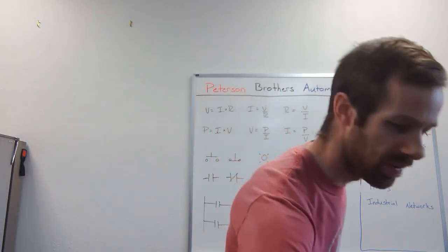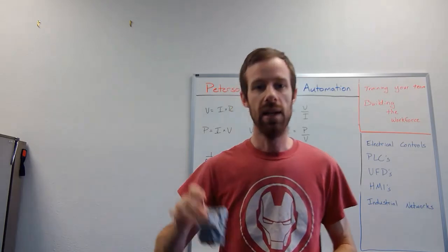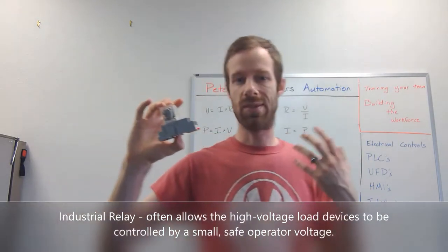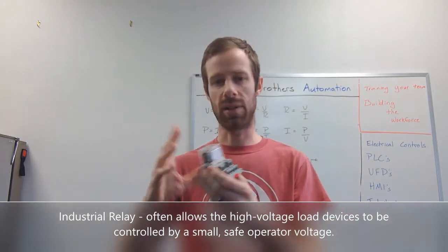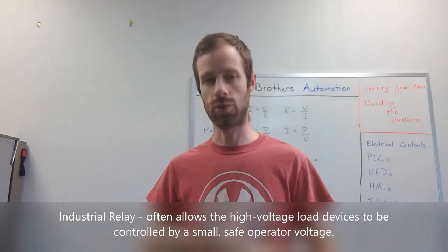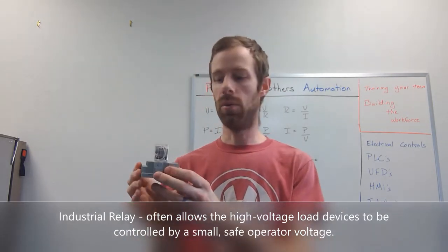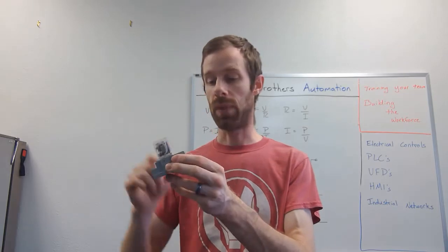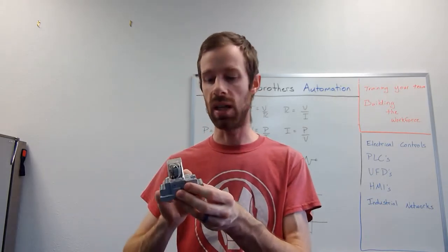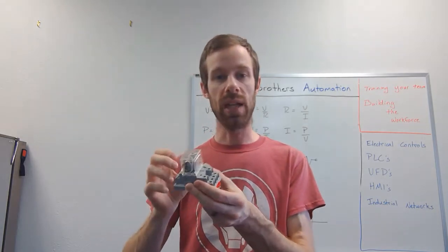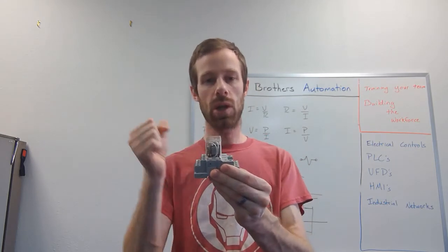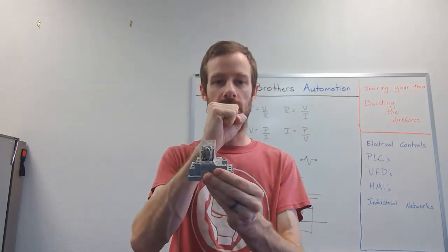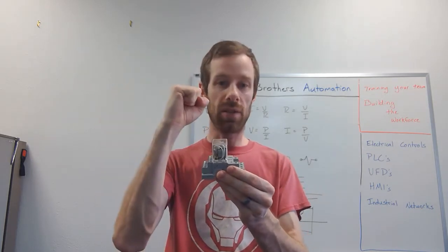So a couple of examples of those kind of things would be the relay. The electromechanical relay is just a really common, kind of a classic go-to industrial control device because it has not only the load, which is the coil, what we have to send electricity into, and its job is to create the motion of little copper switches clicking over into another position. So in one position, they're open. We apply energy, they close.